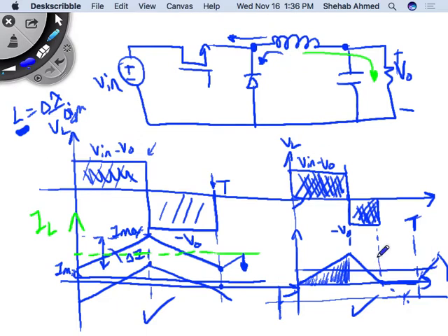So let's say you have a computer power supply that you want to control only in continuous mode. Then you will require a minimum load on the converter all the time. Can you imagine, if you're operating this converter only in continuous mode, that means you have to have a minimum value of load present all the time.